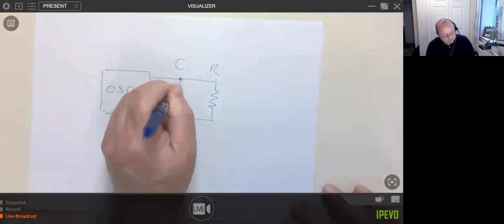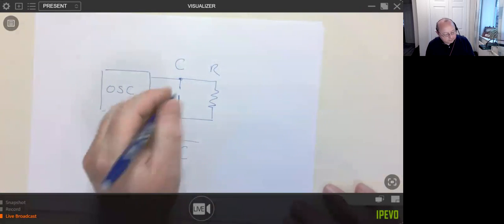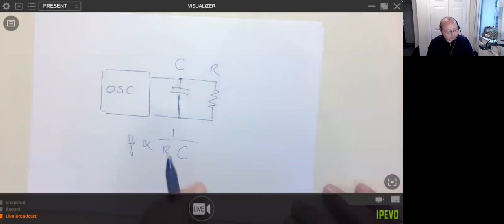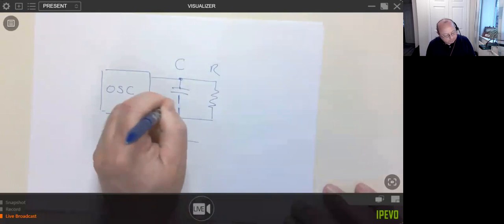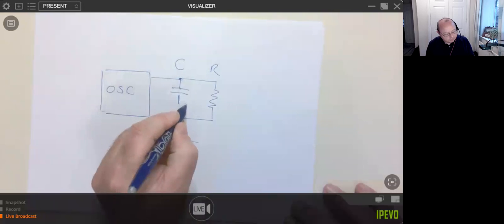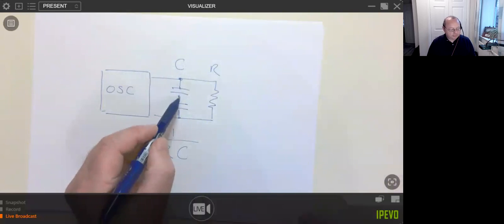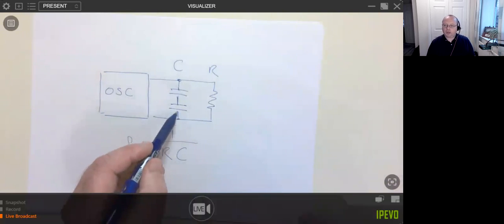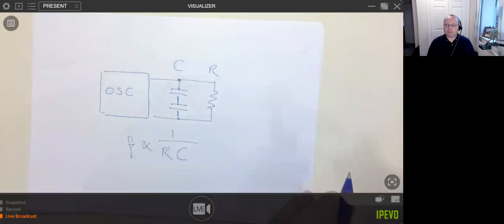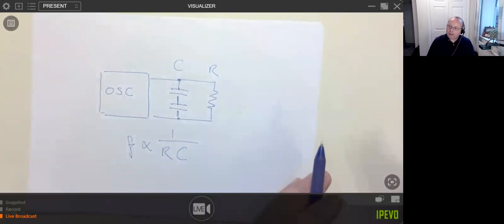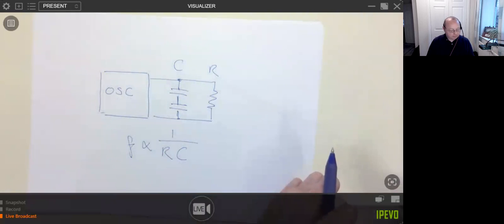The way I got around this being safe, and it's painfully simple, was I just added another capacitor into the circuit. So if it did short circuit and fail, you'd still have some time and some therapeutic effect. It wouldn't be ideal or optimum, but it would still do its job and it would still be safe. You wouldn't end up causing the patient harm, which is really critical.